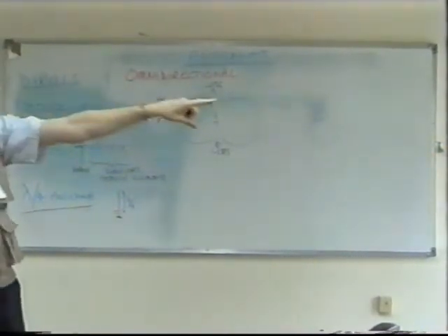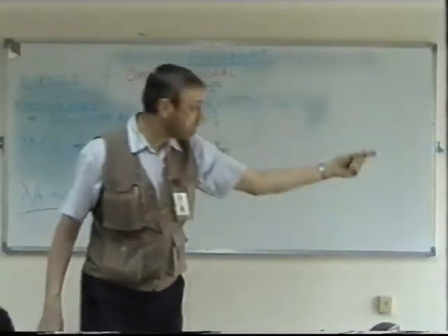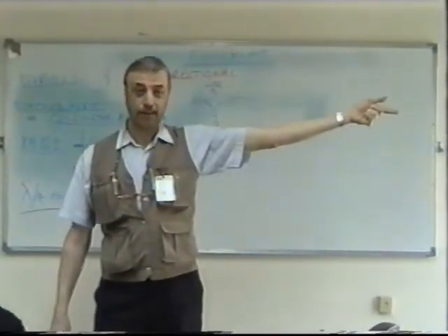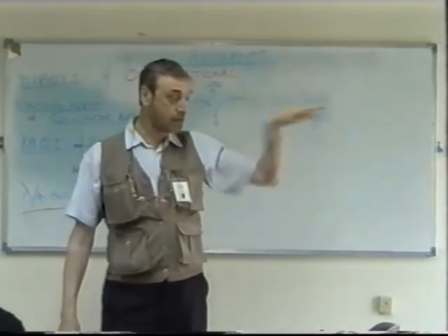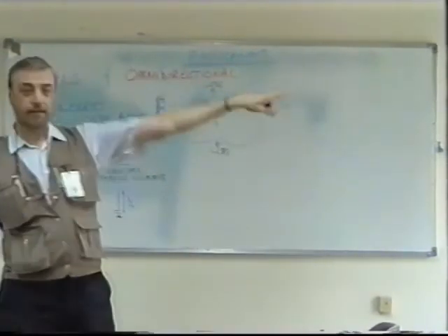So microwaves are good for point-to-point communication, a much cheaper alternative than using cables. We'll talk a little bit more about that in a minute. You have to have line of sight. You've got to see the microwave dish. If you can't see the dish, forget it. If you've got a dish the other side of this building, even if it's just across the road, forget it. You're not going to communicate from here. You've got to see it, all the way through.